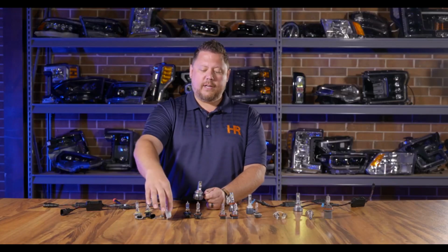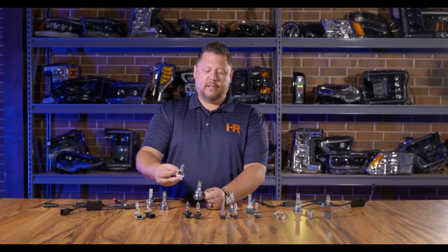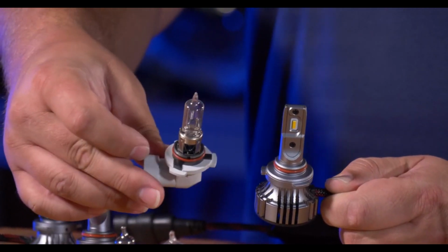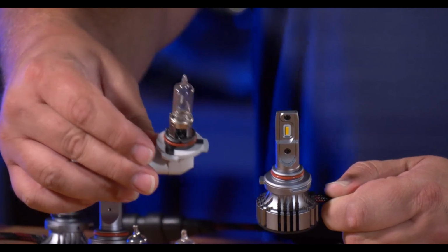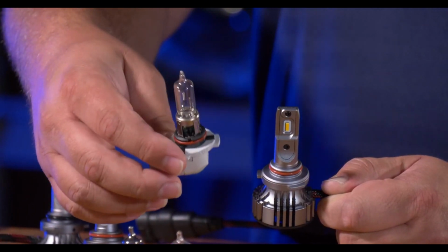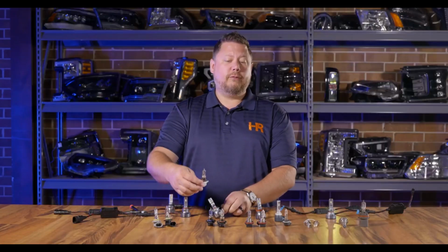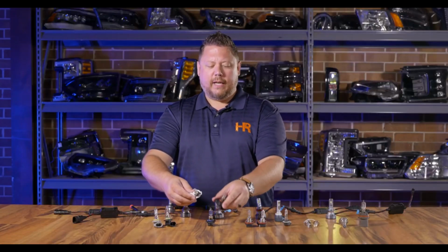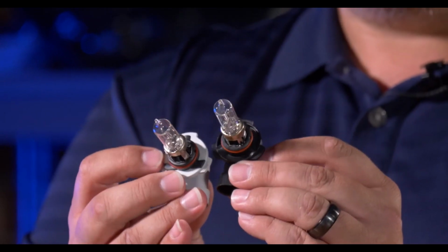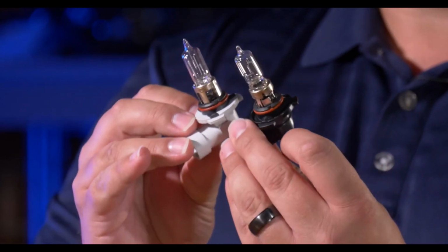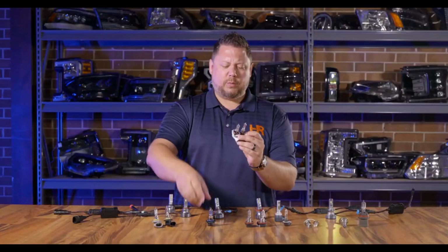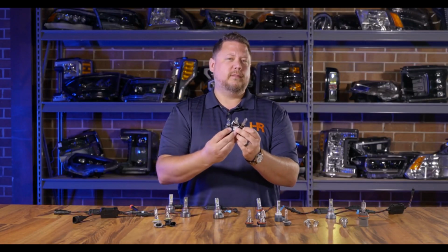And then a brighter bulb, the 9011 or the HIR1, is again pretty much the same bulb, but it's a little bit brighter. Now that's confusing. Why would you use a 9005 to replace an HIR1? Well, the reason is because these manufacturers take the same plugs, the same mounting collars, the same O-rings, and they just make the inside part of the glass where the filament is a little bit brighter.